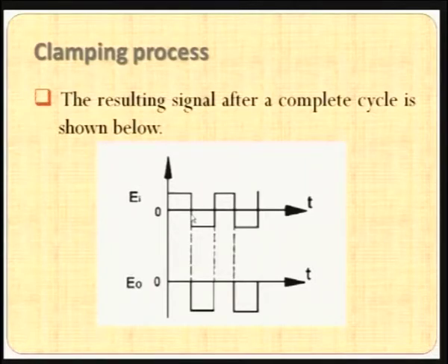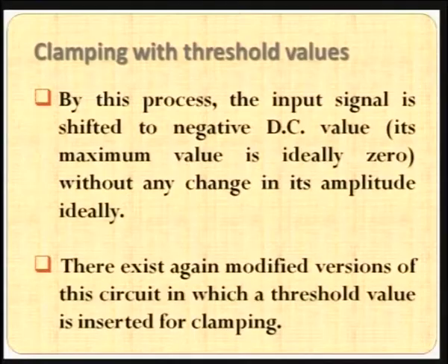So, the charging time is fast and the discharging time is very much delayed, thus the voltage remains constant. That concept has been used there, but in this case, as the input is varying quickly depending on the frequency, the discharging should also happen quickly, so that the waveform is not altered. So, here the RC value will be very small. Let us see how the RC value is chosen.